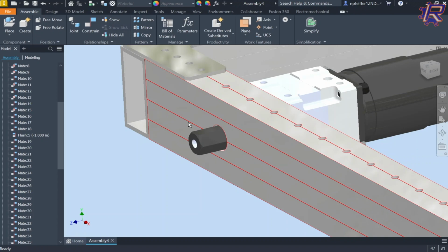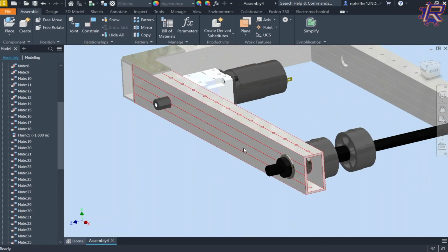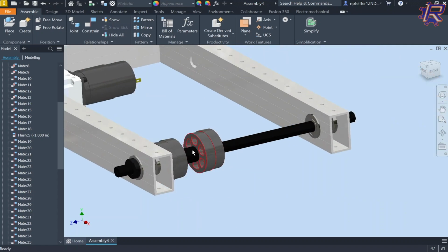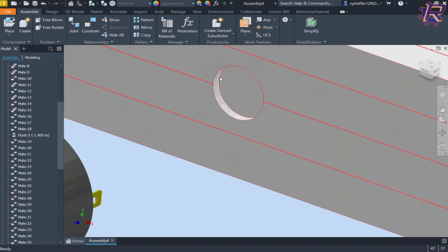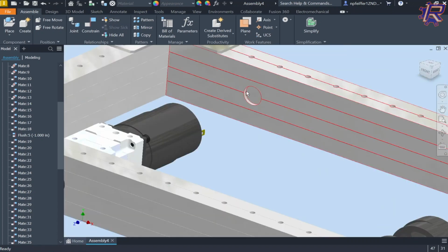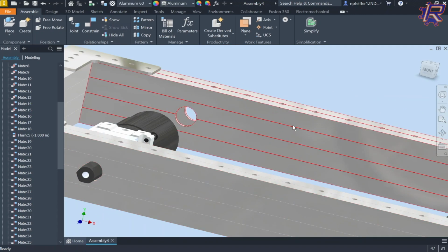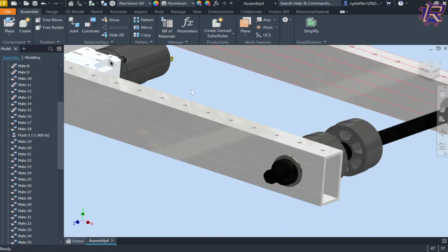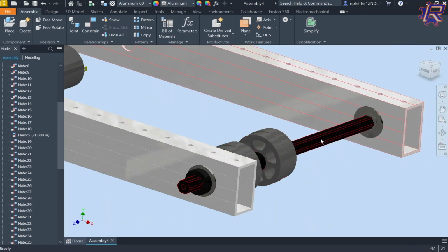And what we can do is attach a pulley on the edge of this axle and a pulley over here. And then we attach a belt in between these axles. So when this motor spins, when it's given power, this axle spins, which means these wheels will spin. As a result, oh, by the way, you'll notice there's a hole over here. That's a bit of a problem. We probably should have used separate parts for these because they're non-symmetrical. But anyway, when this motor spins, if we have a belt running between these axles, this spinner assembly over here will also spin.